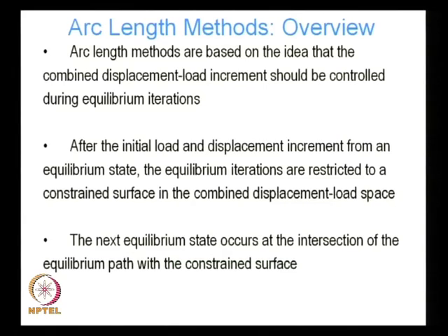We are saying that neither the displacement increment nor the load increment should exceed certain cutoff values during the equilibrium iterations. This will help my nonlinear iterations to converge.